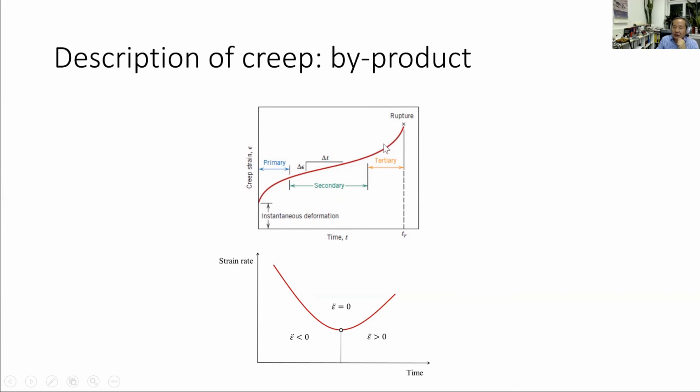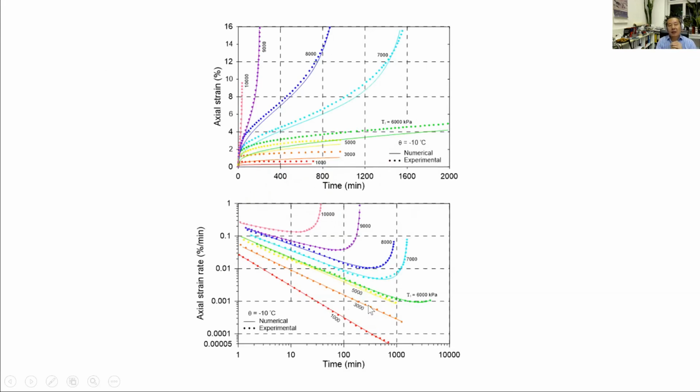Sometimes you get a tertiary rupture, sometimes not, depending very much on the stress level. Then the deformation starts to accelerate again, with the acceleration larger than 0. So the turning point here is of course acceleration equals 0. We have a constitutive model with the acceleration, and it gives you a tool in hand because we can naturally study this kind of behavior. This is what I show you, and how we can reproduce the material behavior and the testing results in the laboratory.